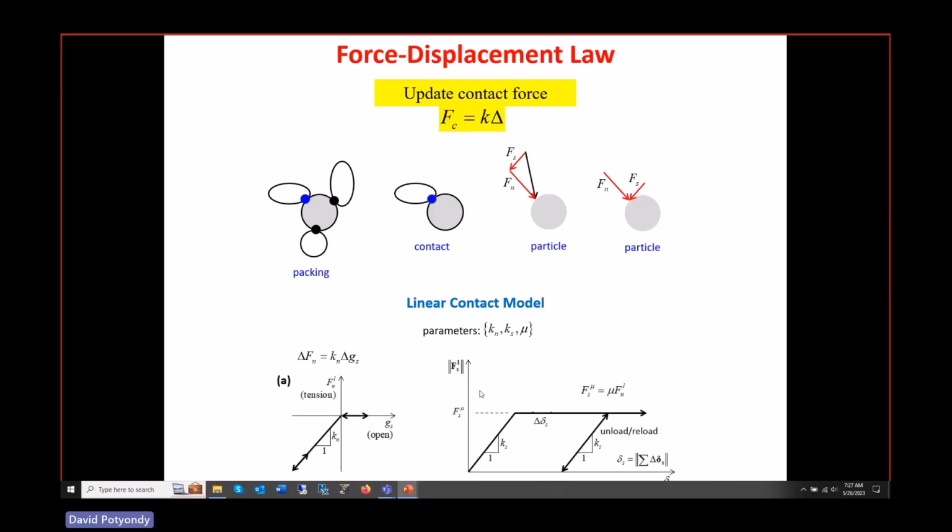Now talk about shear. This is the fundamental thing here. So this is the magnitude of the shear force, right? Because the shear forces could be acting in 2 different directions. And in 3D, it's just basically a force that's acting. Think of between 2 spheres. Now you think of a disc-shaped surface that has a normal that's directed along the line normal to the shears. And on that disc-shaped surface, you have a shear force. So let's talk about the magnitude of that shear force and the relative shear motion.